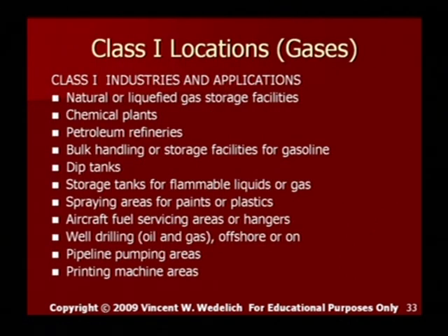Class 1 locations are gases, Class 1 industries and applications. You'll find Class 1 locations in natural or liquefied gas storage facilities, chemical plants, petroleum refineries, bulk handling and storage facilities for gasoline, dip tanks, storage tanks for flammable liquids or gases, spraying areas for paints or plastics, aircraft fuel servicing areas or hangars, well drilling, oil and gas, offshore or on, pipeline pumping areas, and printing machine areas.